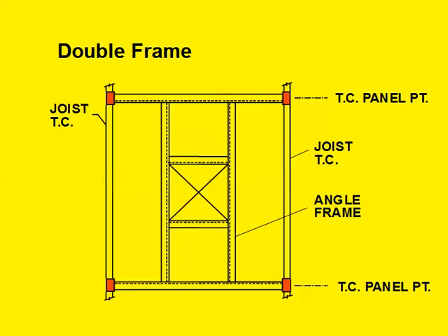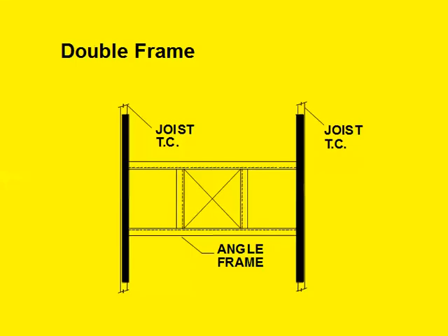But this frame works fine. You may have to reinforce if it doesn't land at a panel point. In recent years, I've used a double frame as I've shown here. Again, the unit sits here. Here's a joist. Here's a joist.